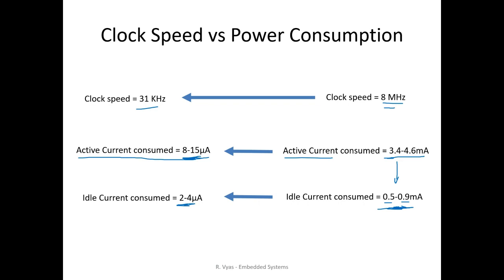It's nothing. And if you're using sleep modes and deep sleep modes, in which many of the peripherals are also turned off, except for a few critical ones, then the current consumption goes down to the nanoamps range. So if you're running things on a battery, you have to move the clock back and forth. For certain speedy applications, you want to run the clock speed at 8 megahertz. But for many applications which are slower, you want to throttle down the clock to lower than 8 megahertz. Questions?